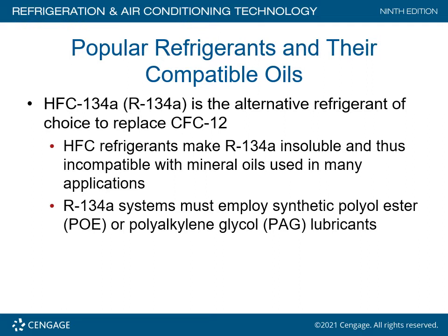So from a retrofitting standpoint, if you have an old system and you're putting in R134a, you have to change the compressor oil. R134a systems must employ synthetic polyol ester, POE, or polyalkylene glycol, PAG, lubricants. The PAG lubricants you will find in automotive technology, whereas the POE you're going to find in residential and commercial compressors.